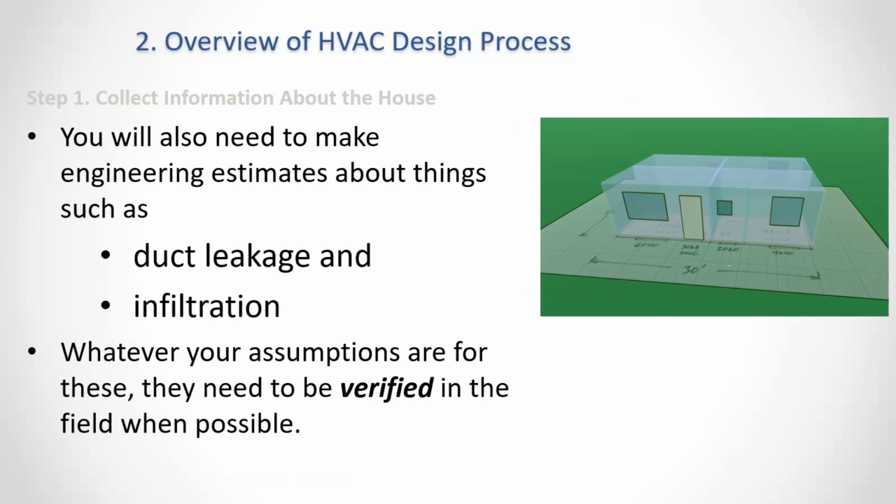So when I do a load calculation, I assume average or better leakiness, even if I suspect the house is quite leaky, because you're not doing the homeowner any service by putting on a bigger piece of equipment because their house is leaky. To me, that's just dumb. It's like putting a bigger engine in your car because your tires are flat, right?